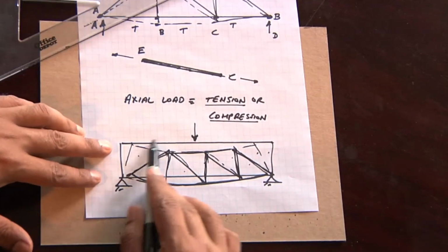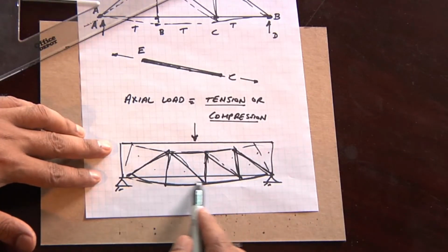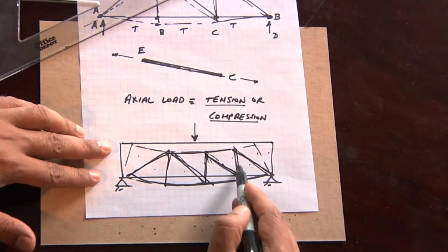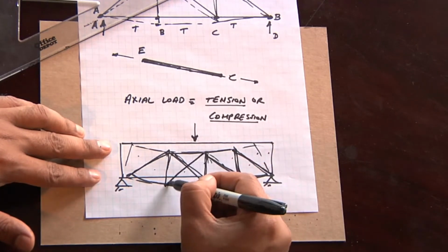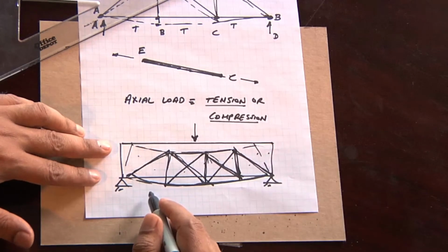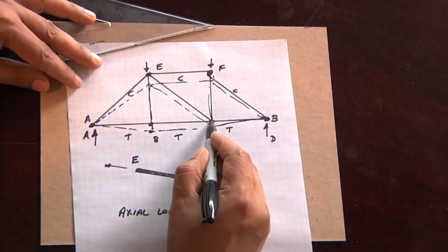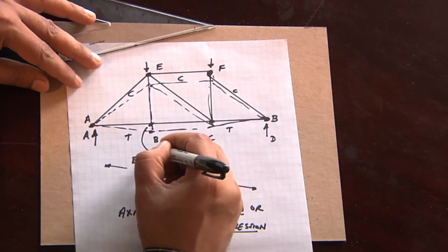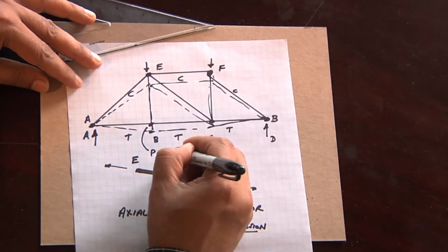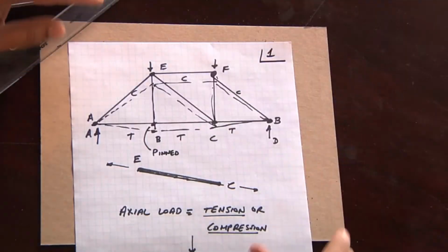In every beam there's an embedded truss, where you have diagonal members. In this case, we may have double diagonal members. So every joint in a truss is a pinned connection. That means that there is no moment. I'm going to label this sheet as sheet number 1 for module 5. Let's take a look at the next section to understand what we mean by a pinned connection.